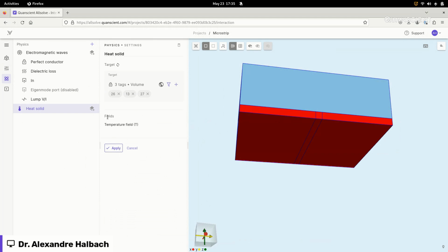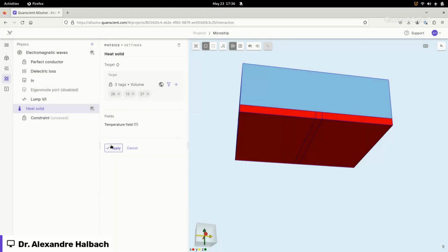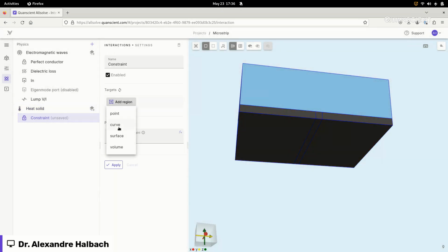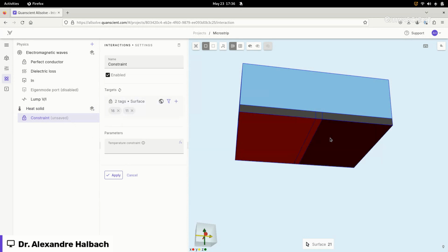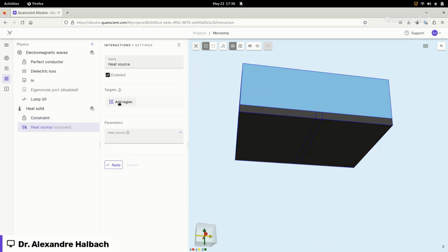And we're going to define, as usual, a thermal conduction simulation, like a lot of our customers do quite routinely. So nothing fancy here. You define a thermal ground, for example, with a reference temperature. Here it's relative, so you can consider that it's the temperature delta. And then the next thing we need to do is add a heat source. So it's going to be a volumetric heat source that depends on the electric field. And there's a formula for that you can easily check online on Wikipedia or whatsoever.